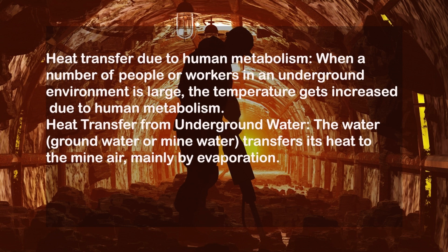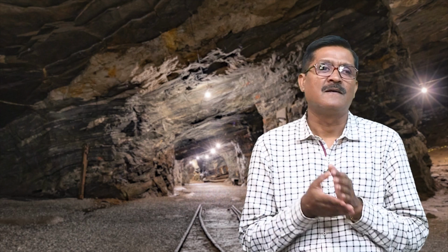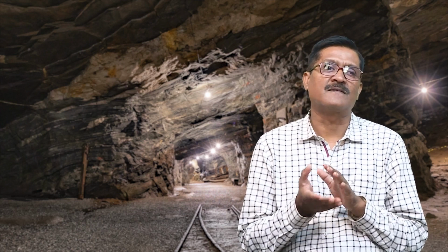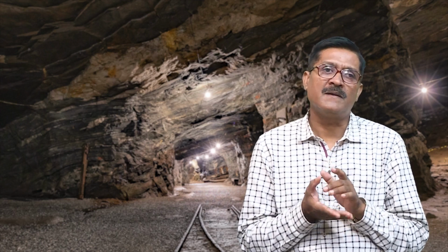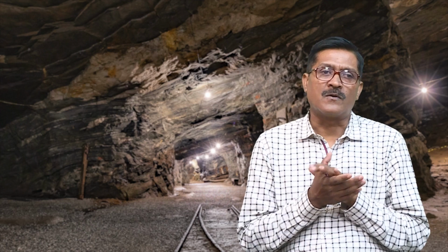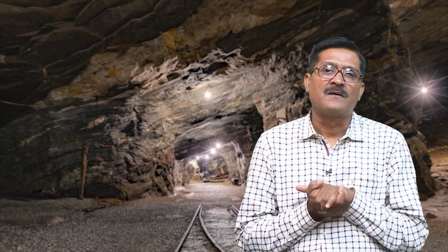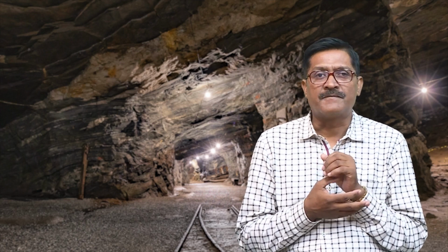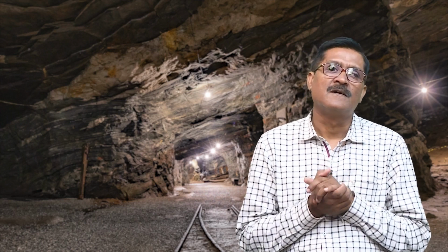The underground water transfers heat to the mine air mainly by evaporation, because as we go deeper, there is presence of water. This groundwater comes through the strata by exudation, by percolation, and they get accumulated or even flow through the roadway of the mines. This water, when evaporated into mine air, gives rise to moisture content of air, as well as the temperature of air also gets increased.